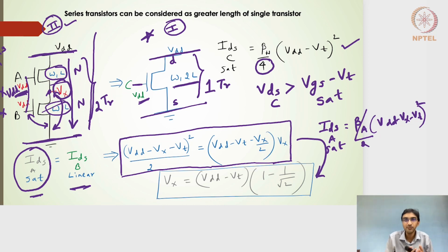Generally, when we are manufacturing on a particular wafer, where we extract multiple chip designs, we tend to have the same channel length. But because I've written two different channel lengths here, L for configuration 2 and 2L for configuration number 1, just to make it simple, those two chips or wafers are completely fabricated separately.